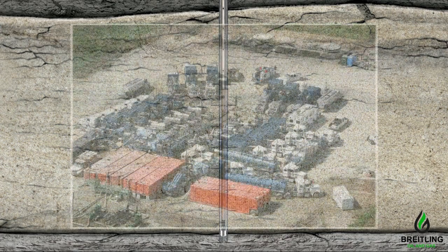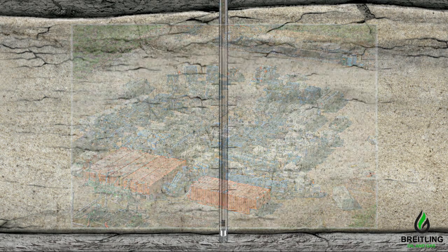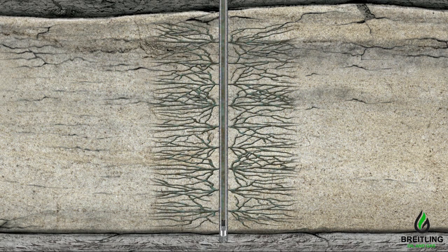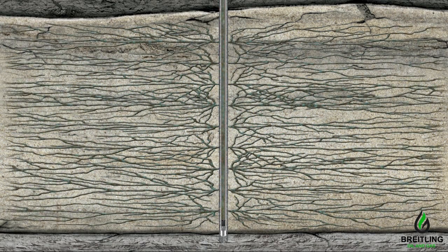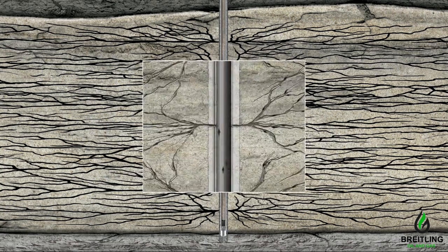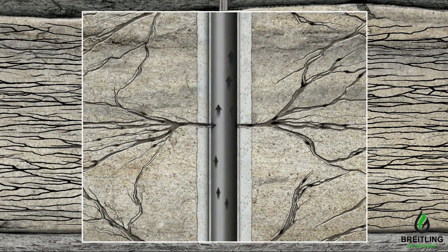The next step is to hydraulically fracture, or frac, the zone. Here, sand or other proppants are pumped into the wellbore under extremely high pressure. When the mixture reaches the target zone, the pressure forces it out through the perf holes and out into the sandstone formation, causing it to fracture. This creates a fairway connecting the reservoir to the well and allows the released oil to flow to the wellbore.